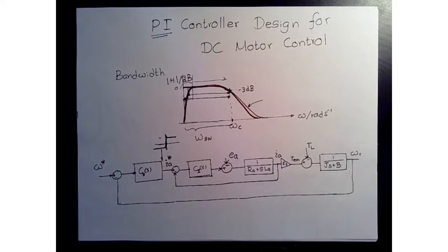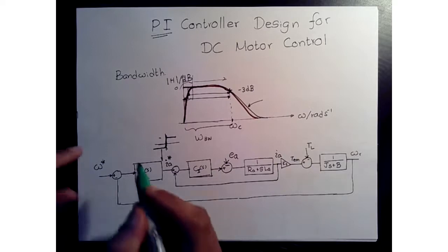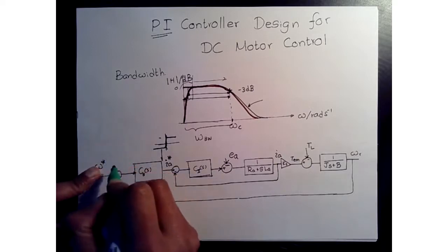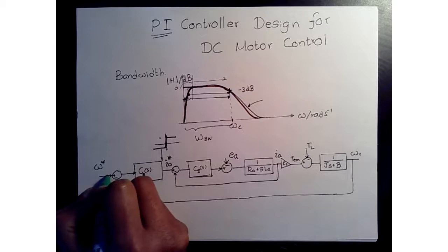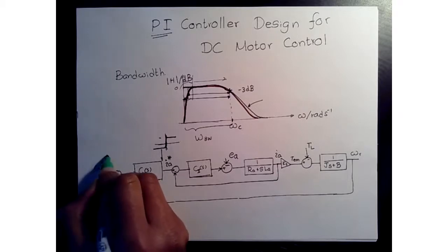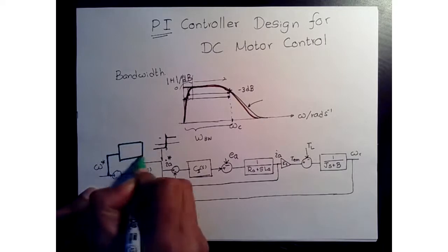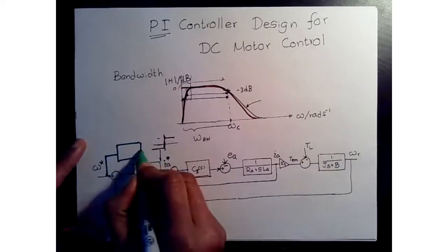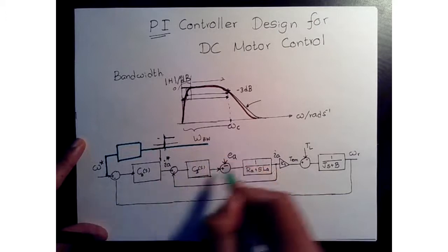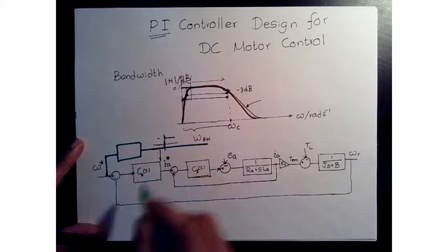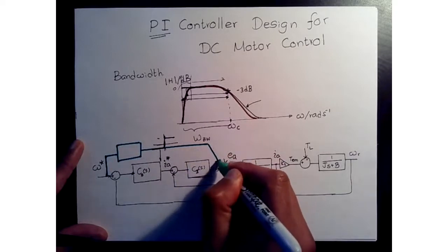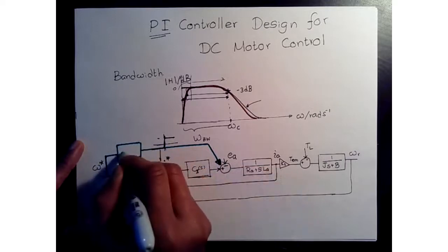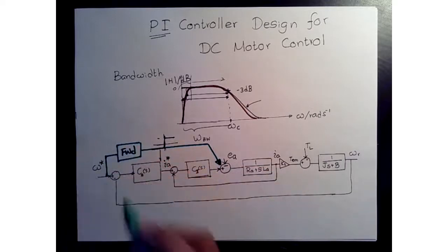Now, another practice that people follow is feed-forward control. The feed-forward control loop comes in right here. So you have your reference changing. Depending on the information you have about your system, rather than letting the dynamics or the commands pass through the closed loop, you can directly influence the applied voltage based on the information you have about the speed.